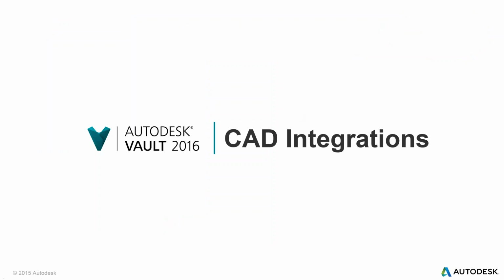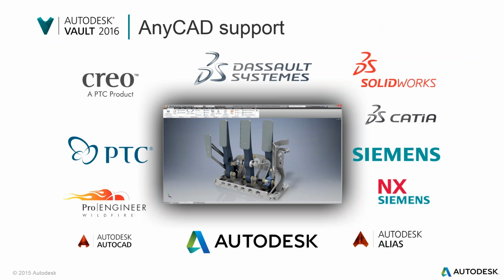The first one was really being driven by Inventor 2016 functionality called AnyCAD, that ultimately now adds the functionality of referencing third-party design tool data. Historically it would have translated it into a dumb model that was then used in context to the Inventor model. So in this case now we reference it, and if there are changes in the originating design data, those changes, through an update within Inventor, will flow that data back in and update inside the Inventor model. So a very powerful use case.